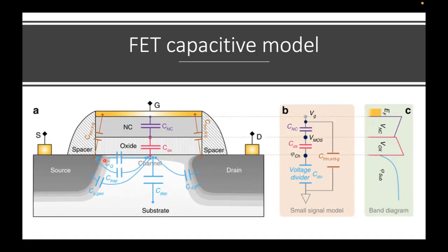Finally, we have two other types of capacitance. We have a capacitance between the drain, the source and the channel itself, because the level of the doping in the source and the drain and in the channel are not matched. Usually, the source and the drain are with N++ doping, high doping, but the channel is an inverted region with slightly lower doping, creating a capacitance here. And finally, we have a somewhat diluted effect capacitance, which is due to the trapping effect, and we call it C-trap here. So these are the different capacitances inside the MOSFET.